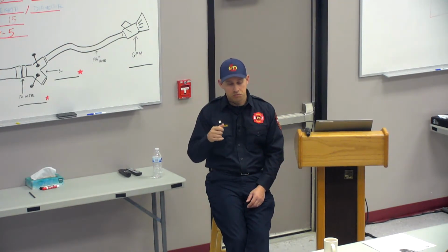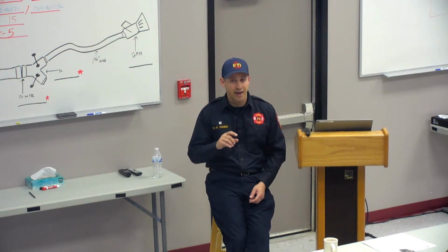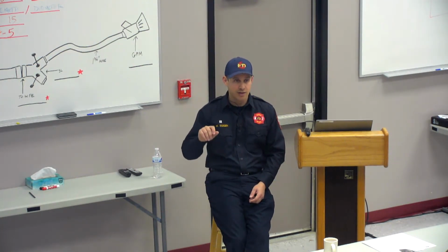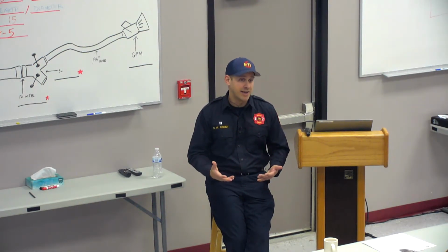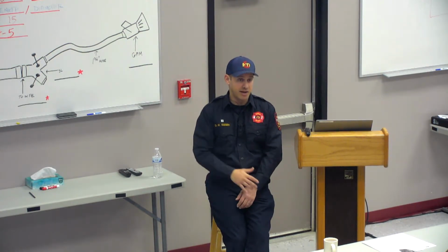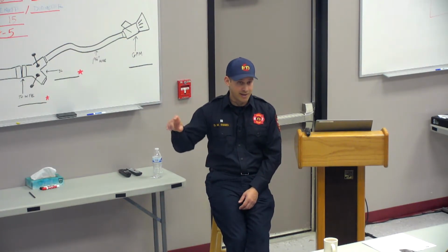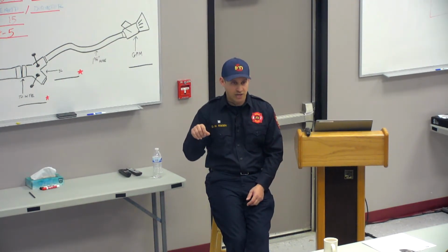So me personally, I would come in every morning, make sure it operated, on, off, see if I could change the setting, and I left it off. That was how I did it. And anytime I pulled a hand line, I turned it on and set it to that one. That was my method. I'm not saying that needs to be yours, but I do think a consideration needs to be made that we understand transfer valves and pressure relief valves and when we use those.